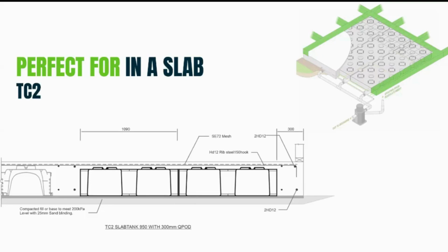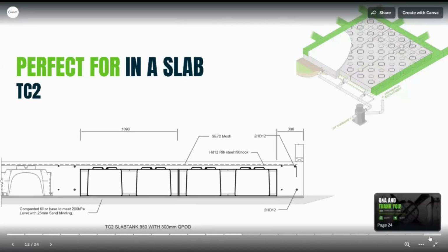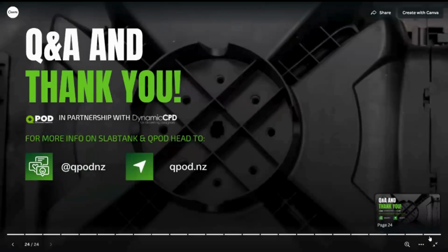And yeah, more of a comment, I suppose. Designers will need to watch placement of bottom plate fixings. Some tradies are better than others at drilling bolts to floors.